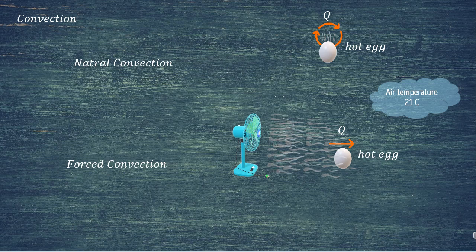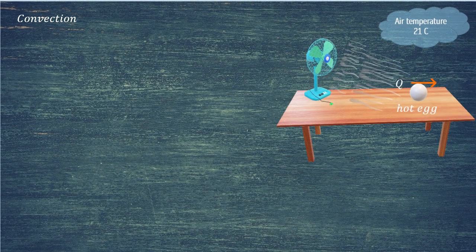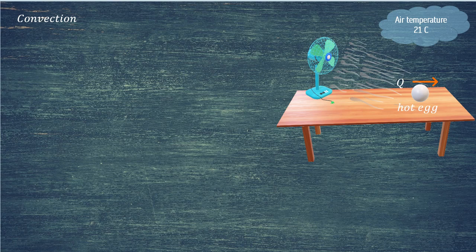For instance, without a fan, heat transfer from the surface of a hot block involves natural convection, driven by the rise of warmer, lighter air near the surface and the descent of cooler, heavier air to fill the void. If the temperature difference between the air and the block is insufficient to overcome air resistance, heat transfer occurs through conduction without initiating natural convection currents.